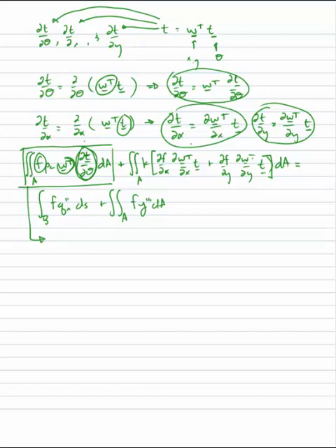T is not a function of x and y, so we can pull that out of the integral, just like I could pull this T and this T out of these area integrals. So if I do this, I get the integral over the area of F times rho c times W transpose dA, and then I'm multiplying it by d temperature d theta. And this is W1, W2, all the way to W sub n, and this would be d theta of T1, T2, all the way down to T sub n, like that.